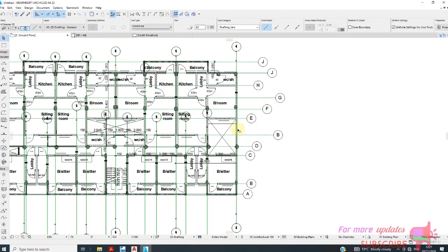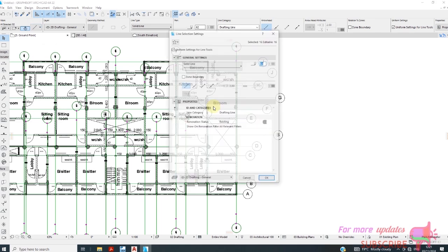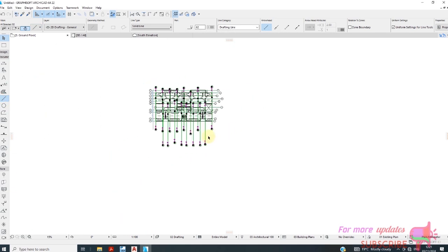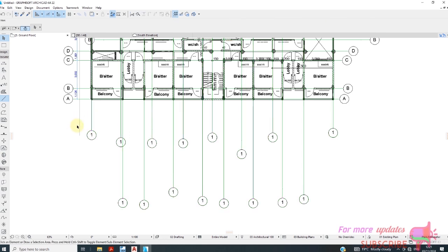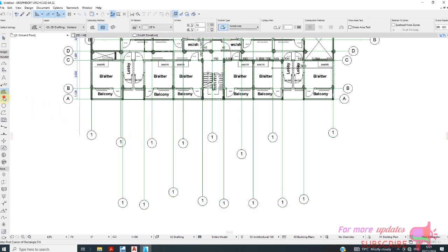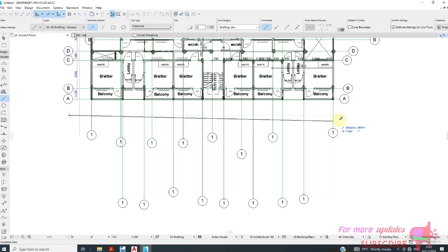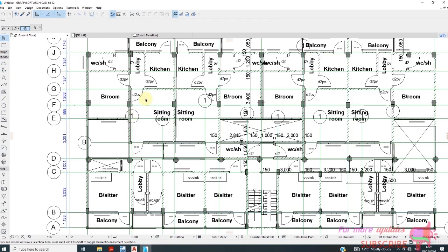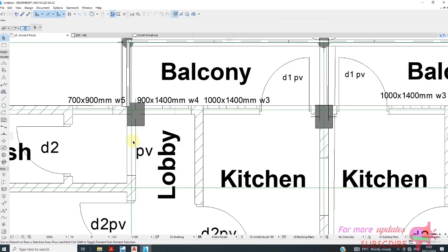Okay, so I want to activate the line tool. Escape, I'll activate the line tool. From here, holding shift, there. Activate another line tool. From there, holding shift to there. So all these will be moving to that same point.